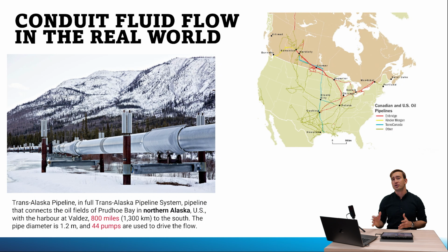In Reynolds' experiment, what he did was he injected a stream of kind of colored dye into a flowing fluid in a pipe. And what he measured and saw was that at low discharge, the stream stayed more or less intact, and you could see the line of colored fluid as it flowed through the pipe. But as you increase the rate of discharge in the pipe, you saw greater and greater turbulence throughout the system and greater dispersion of the fluid, which should make some sense.